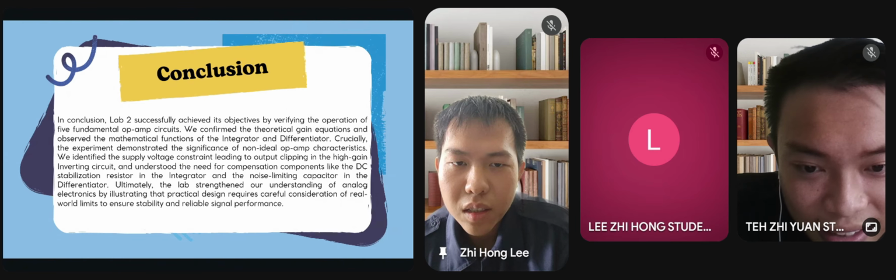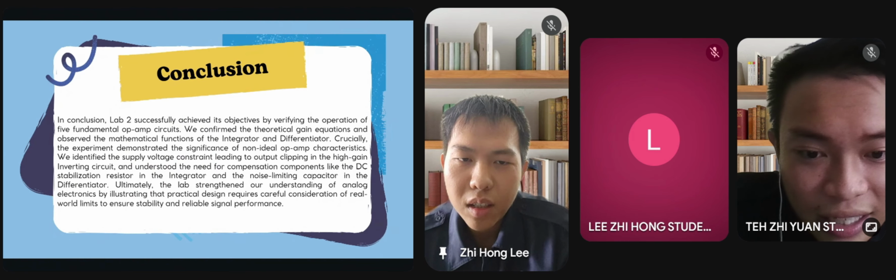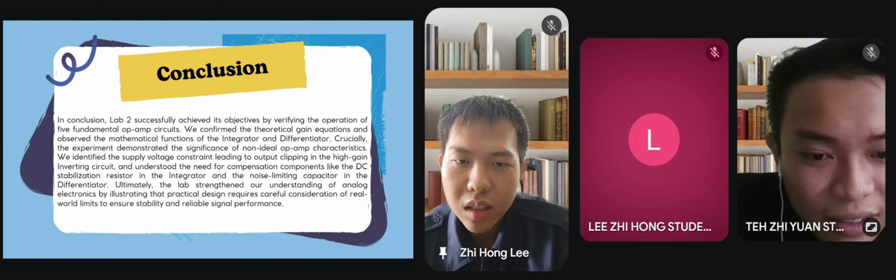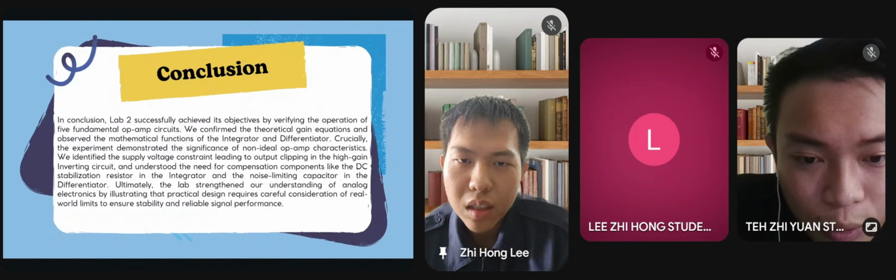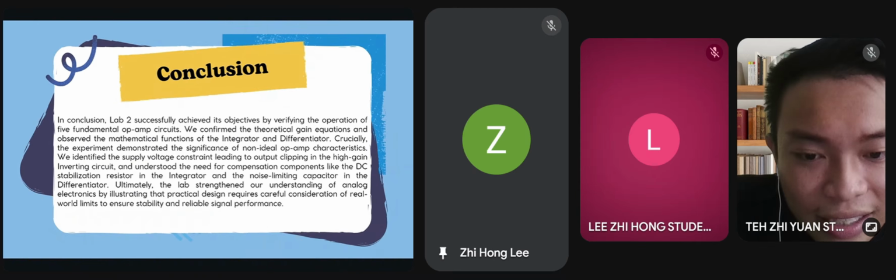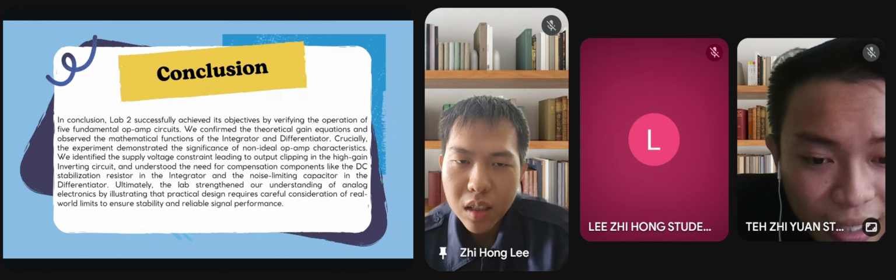We identified the supply voltage constraints leading to output clipping in the high gain inverting circuit and understood the need for compensation components for stability and noise limiting.